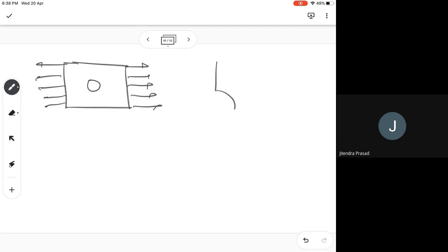In this case, we can analyze just a quarter of it. Why a quarter? Because this will give you the result, and this is symmetric about this, so the same problem you can pose this way. Such tricks you can also use during analysis.